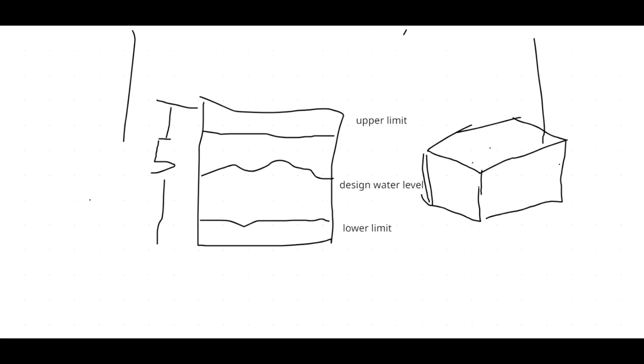This is a design key issue. Ooh, that would be huge. In every tank design, you estimate the height of your tank. There are two different things now. The height of the tank above level is the height of the stanchion, let's say, or the elevation, if it's an elevated tank. But in the tank volume itself, the tank volume will have three parameters, except if it's a cylindrical tank, which only has a radius and a height. But if it is a rectangular tank, we have the height, the breadth, and the length.